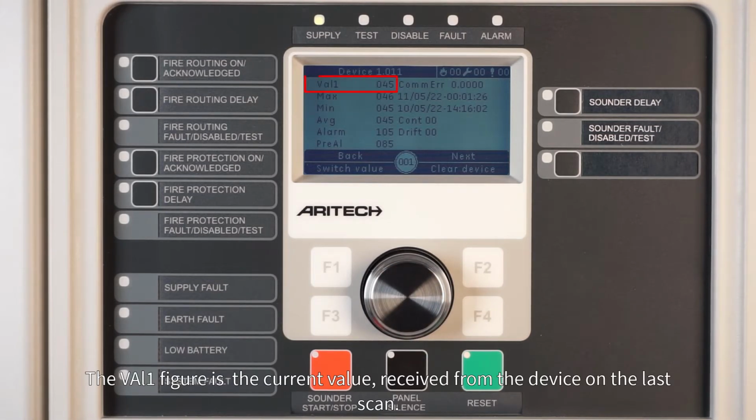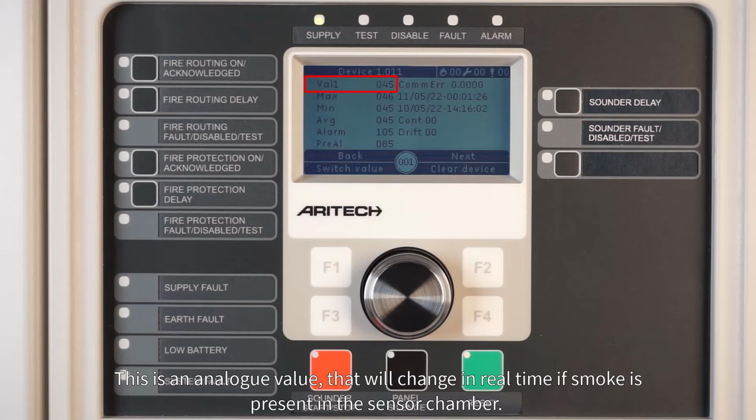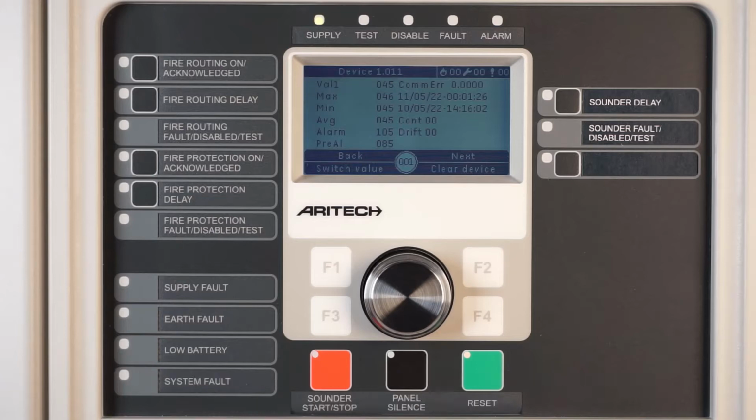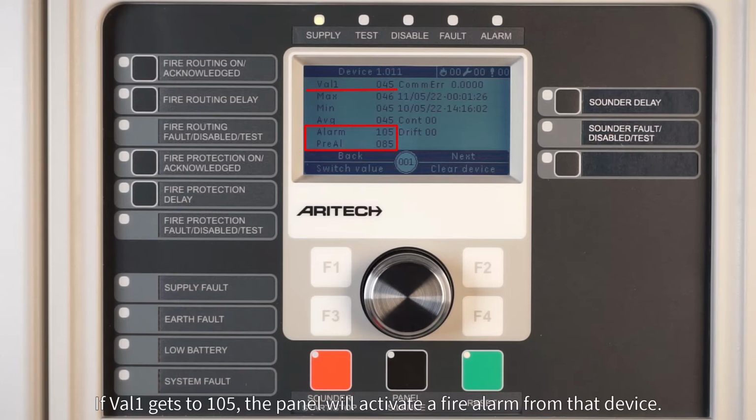The val1 figure is the current value received from the device on the last scan. This is an analog value that will change in real time if smoke is present in the sensor chamber. Looking at the alarm and pre-alarm thresholds: if the value of val1 reaches 85, the panel will display a pre-alarm condition. If val1 gets to 105, the panel will activate a fire alarm from that device. The change in threshold is due to background compensation.